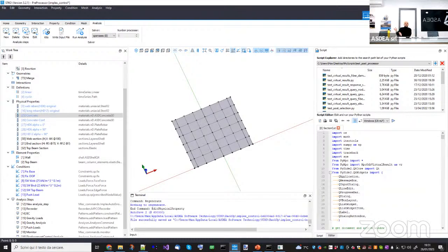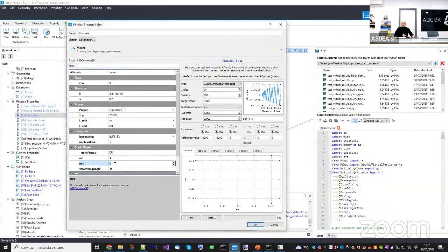I plug it inside the damage tensor and compressive curves, and then I compute a couple of scalars. I don't do anything special. The only thing that may be a little bit costly is if you exaggerate with these values. But simply because, for example, once I compute the eigenvalues, I need to find what is the closest normal to activate the damage in that direction.